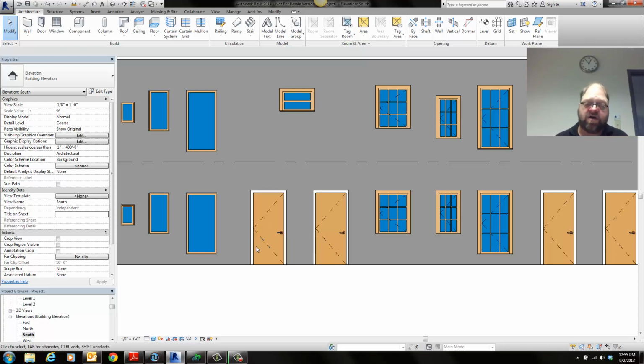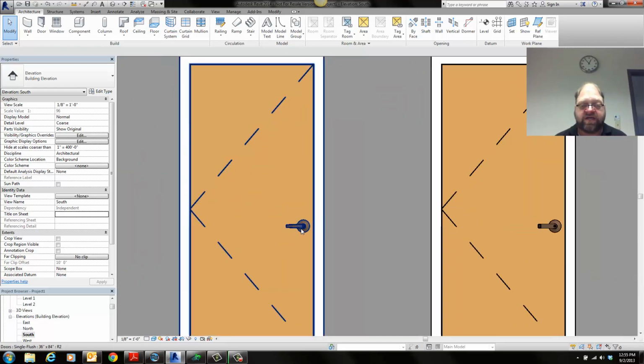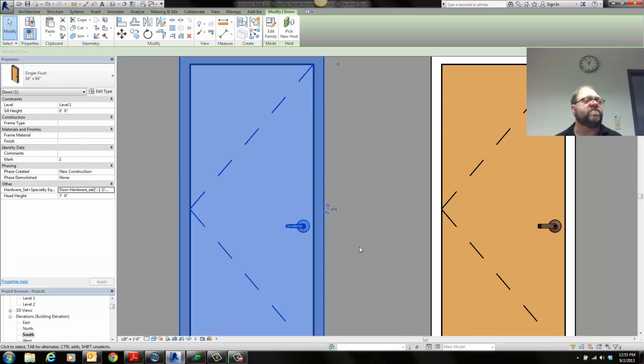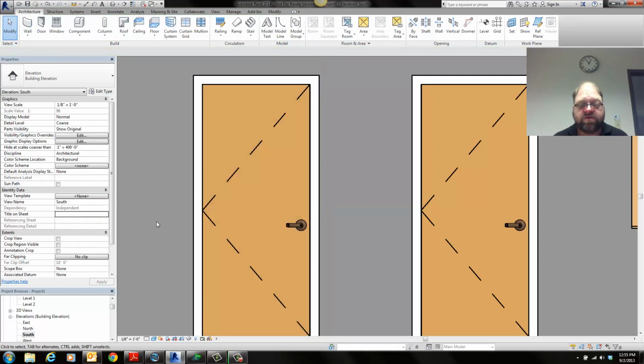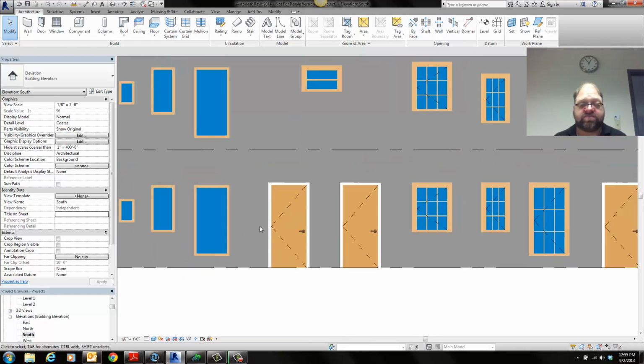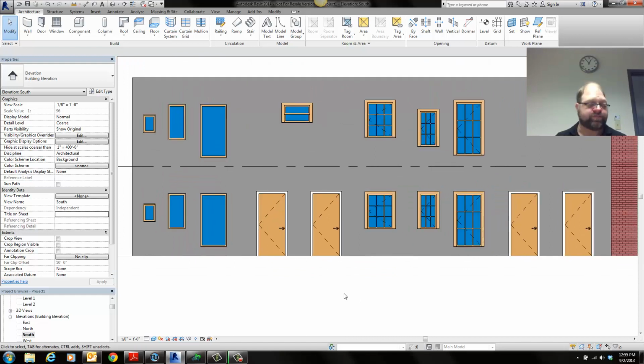Another powerful concept here, which is being used in this case, is that you can nest families together to create something. We have a door family here that has this handle family, which is a whole other family that I'm swapping in and out. Nesting families is pretty powerful, because I have one family description in my project, and if some change comes along, I can change the nested family, and it will change everything in my project all at one time. So that's another way to affect massive amounts of change, with nesting of objects.